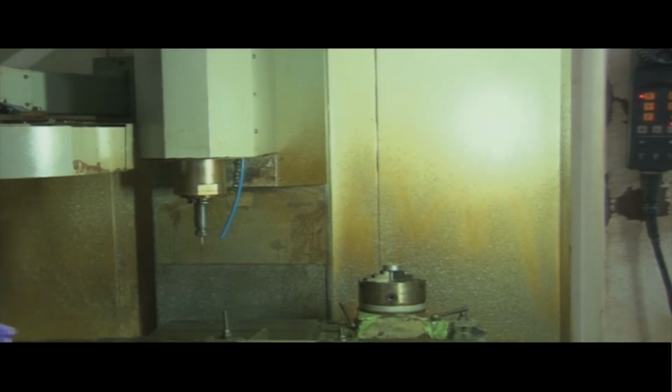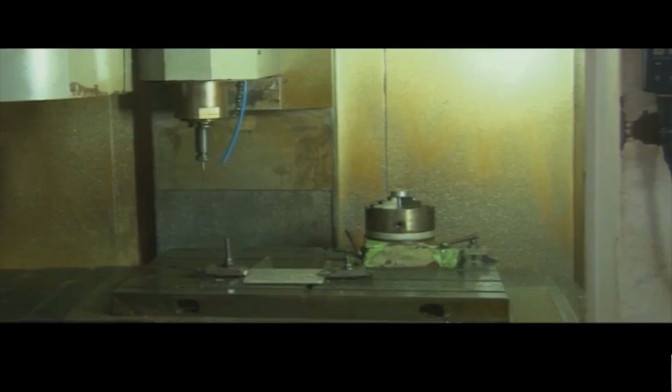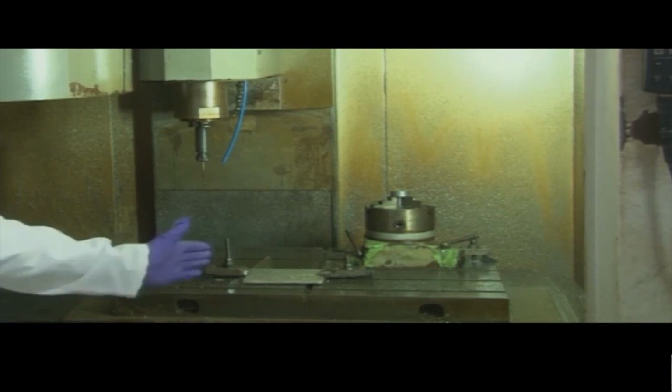So, Z axis provides RPM to the tool, and it also provides feed in Z direction. So, the tool movement is all taken care of by the Z axis here. This is all again done by the pneumatic system. Going downward is minus Z, going up is plus Z. So, depth of cut can definitely be controlled by this.